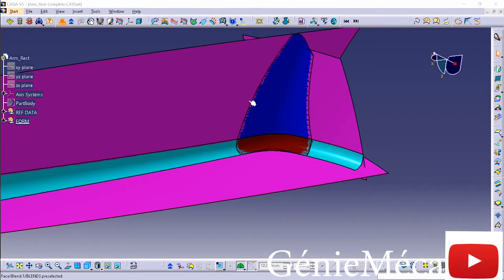And coming off of your primary surfaces, which even though they're the biggest shapes, they should be the simplest mathematical representations of shape in your part. We want to try to minimize the amount of math in these. And the reason is because every downstream function is going to increase the complexity of said surfaces. So the next surface built off of it's going to be a little more complex, and so on and so forth, until we get into our tertiary surfaces. And as you can see here, generally speaking, our tertiary surfaces, these little ball corners, are the last things that we build.